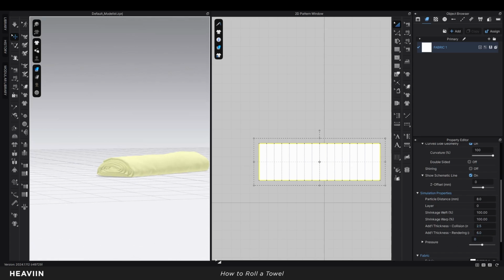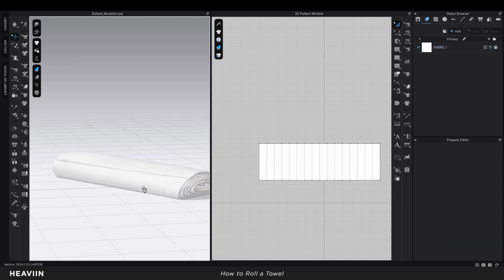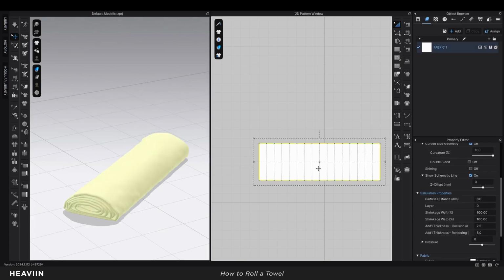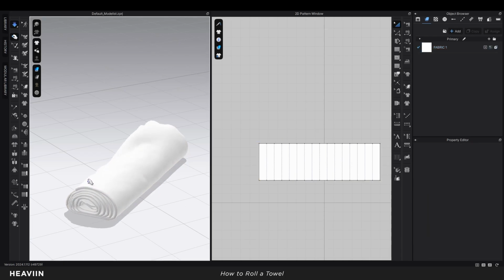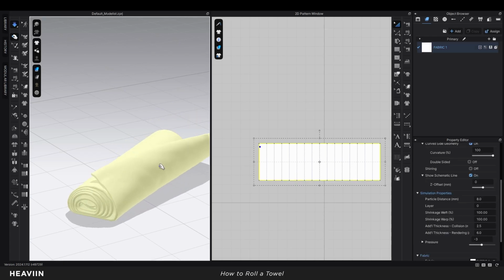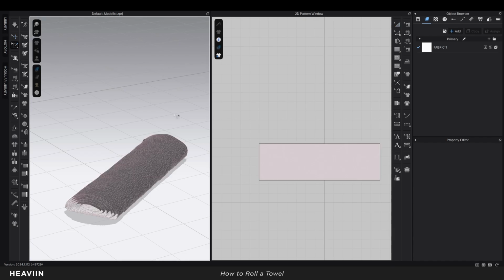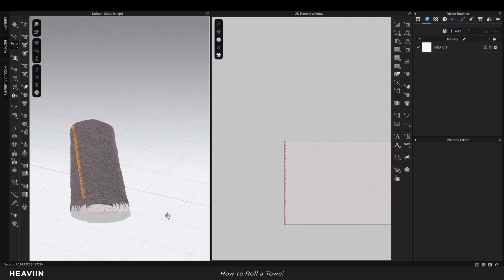All right. So for added volume, all you have to do is decrease the pressure according to what you want. The problem is that if you decrease the pressure, I'm going to show you what happens. If you decrease pressure, the piece that's above the blanket will fall off, right? So if you don't want that, you just have to go back and pin this. We're going to use the pin box tool, and then pin the very edge of this piece, okay?